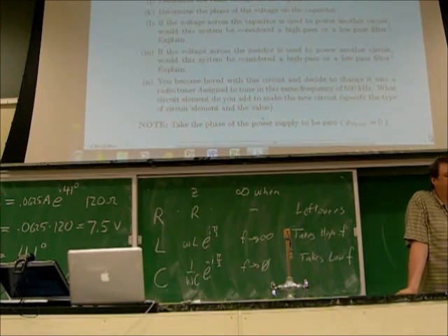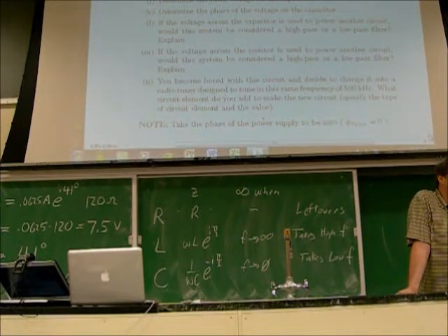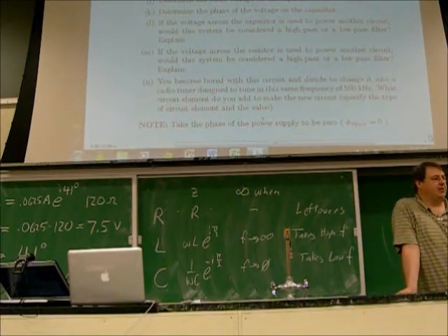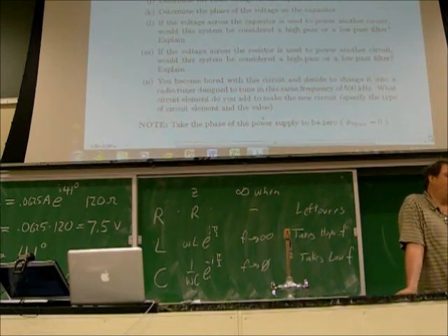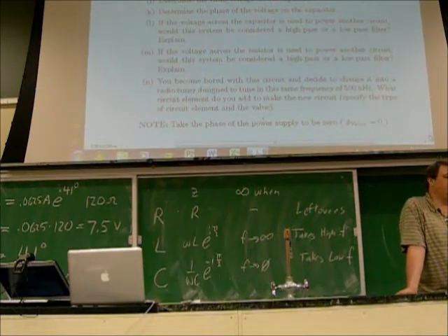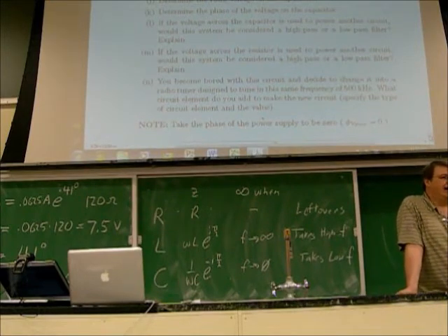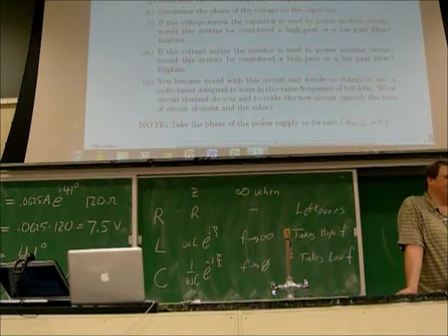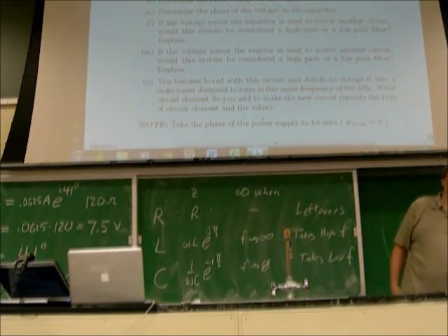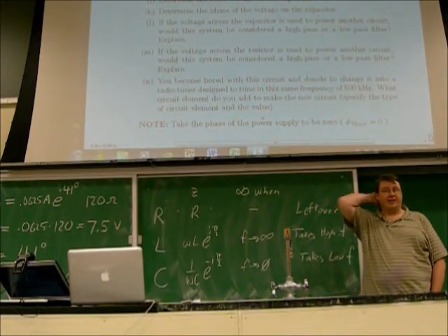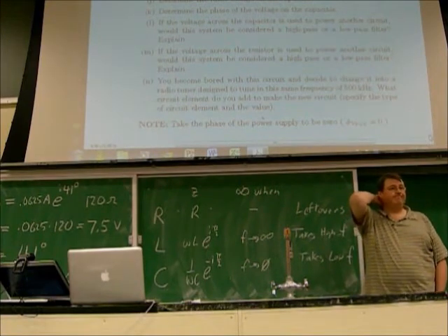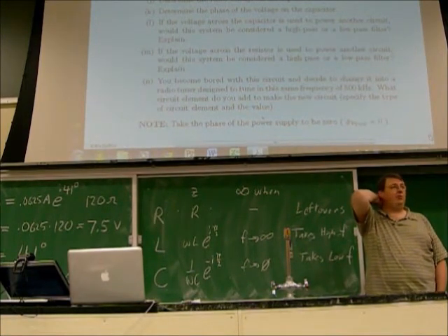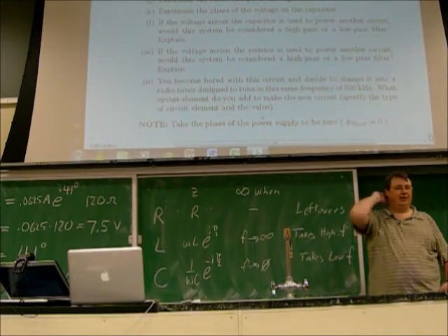So right next to every chip, you put a capacitor, so that the capacitor will suck in the low frequency and the chip will be running on DC voltages as promised. If you went into your computer and desoldered all the capacitors and turned it on, it would probably run for a few minutes before crashing. But you'd like it to run longer than a few minutes. And so the capacitors are acting as low-pass filters. Okay, everybody with me? All right.